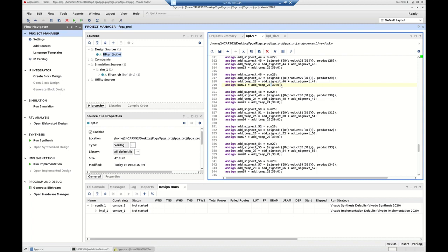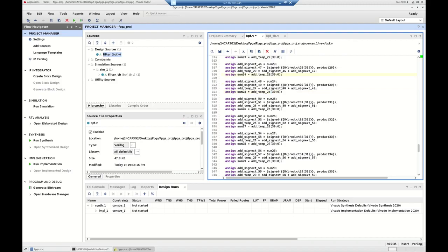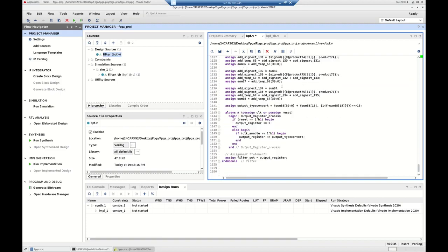After that, what it does is it multiplies the signal with the coefficients, and if the signal lies in the frequency region of the bandpass, it will just multiply it with the gain. If it does not lie within that, it just reduces it. So this is how coefficients are working in this case. As we go really far down, all these coefficients are being multiplied and then being added. At the end of our filter, we can see that output is basically the sum.